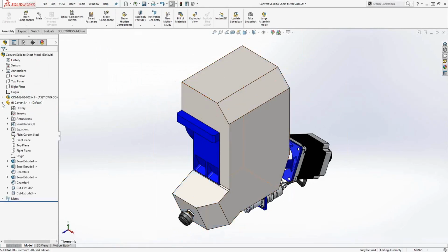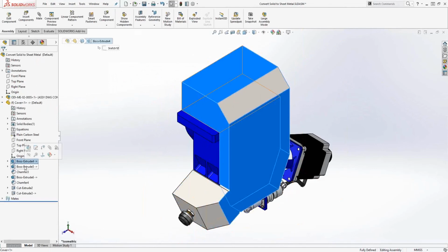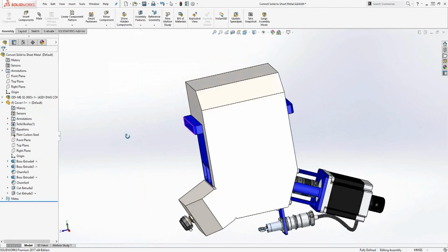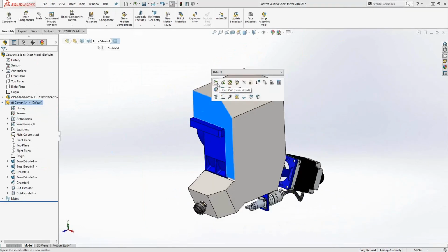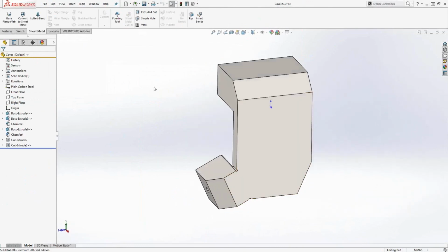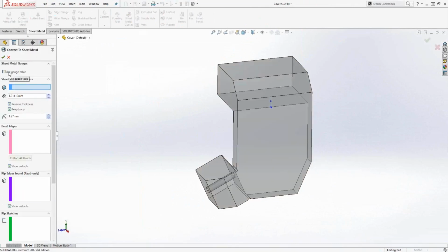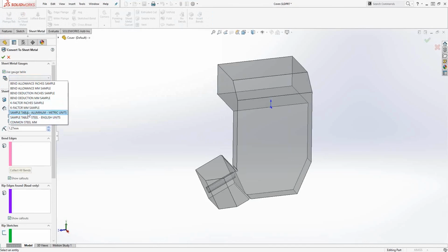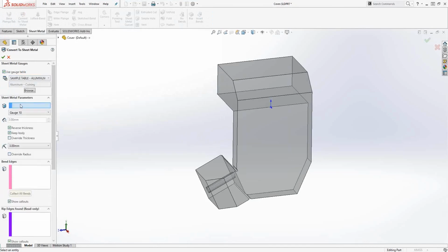this solid geometry using just regular SOLIDWORKS features, right? Just a bunch of extrudes to create a region where you want to create that cover. Now, when I open this part, I can convert this solid body into a sheet metal part very quickly by using this convert to sheet metal. So this convert to sheet metal, you can use a gauge table here as well. Let me see. Convert to sheet metal, metric. And right here, when you hover over it, it says select the fixed entity. So this is going to be the fixed face right there.